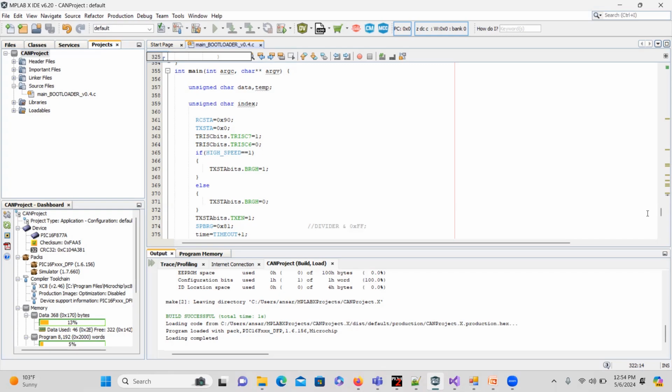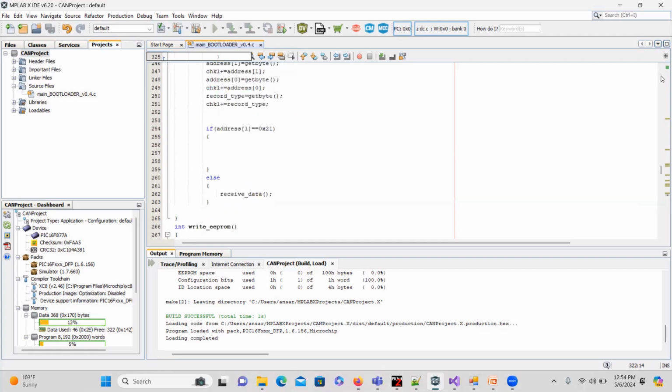Let me do that. When we create an executable, the executable will always be created from the starting address of the microcontroller, so maybe I start from 0. But our aim is to offset the bootloader to the very bottom of program memory. For that, the trick used here, I think I got the idea from their sample code only. Here is an example that they are doing.